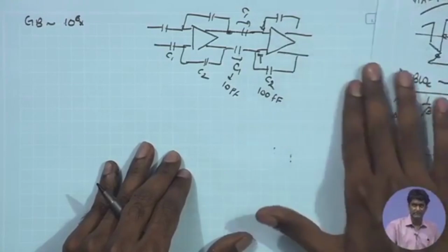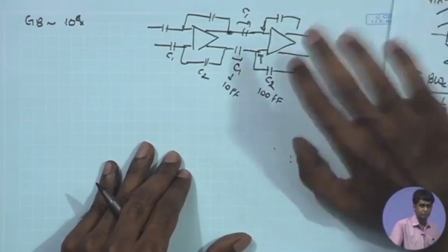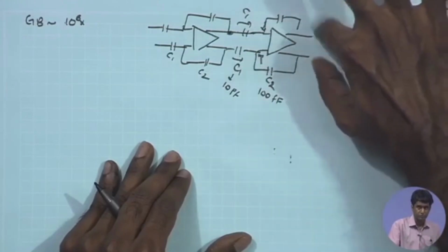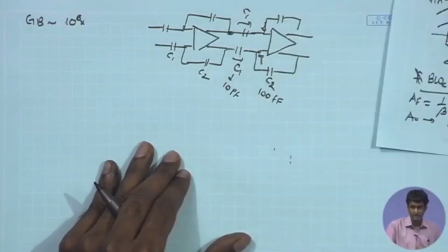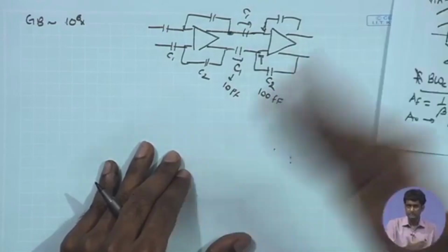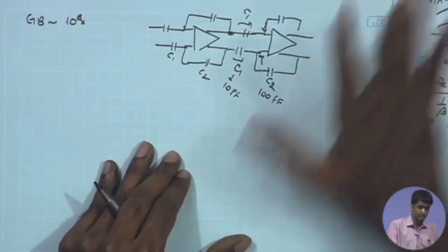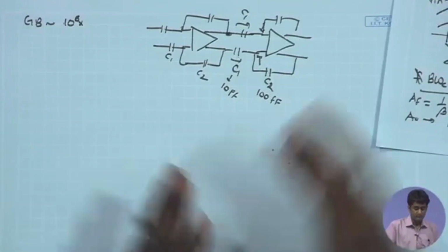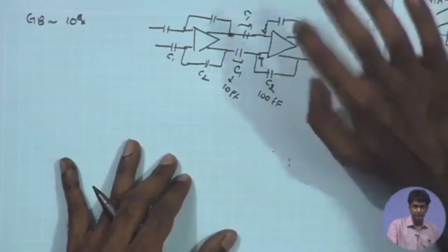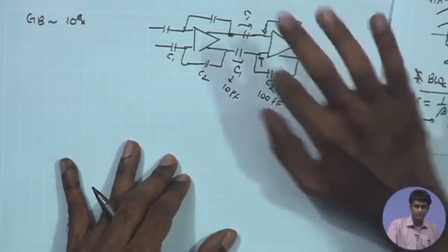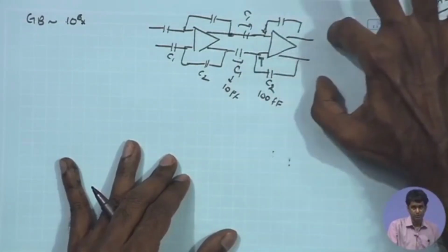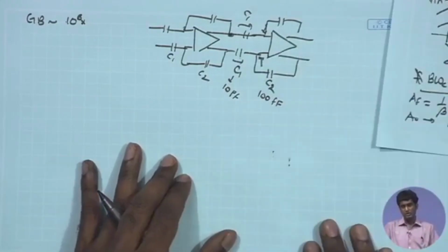So very briefly, we have discussed in the beginning that the ADC has a fixed input range. I would like to map the final amplified and processed output signal to the entire input dynamic range of the ADC. So we will discuss that once we have a discussion on ADC. We will look into the dynamic range concept once again in detail. But if the dynamic range of the ADC is say 1 volt, I would like the output signal over here to always be mapped to that entire 1 volt range, so that the final output peak to peak swing over here is close to 1 volt peak to peak.